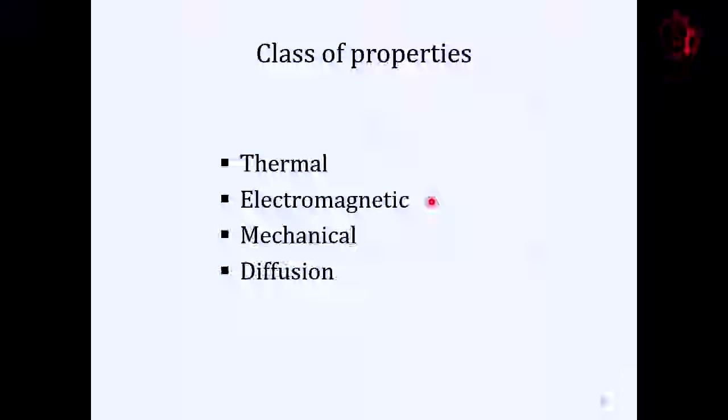Electromagnetic heating, why would this be important? Again, in-package sterilization, because microwave is one of the processes. You want the food to absorb energy, you don't want the package to absorb the energy, especially from microwave. Once the food is heated, of course it's going to give heat to the package, but you don't want the microwave energy we are bombarding to be absorbed by the package and not by the food. So you want to make sure that this polymer has a very, very low dielectric loss factor.